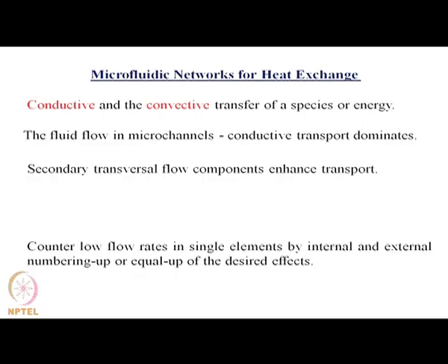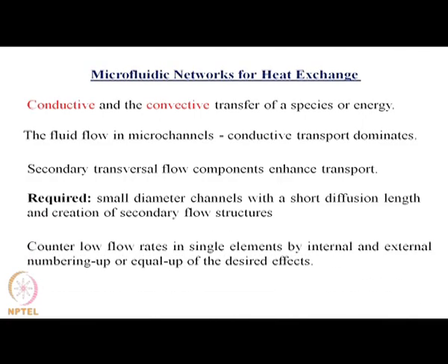Now, the requirement here is small diameter channels with a short diffusion length and the creation of secondary flow structures. If we can have a small diameter channel whose diffusion length is obviously small, and if we can create a number of secondary flow structures, then we are going to get both conductive and convective flow, and we can enhance the transport process.